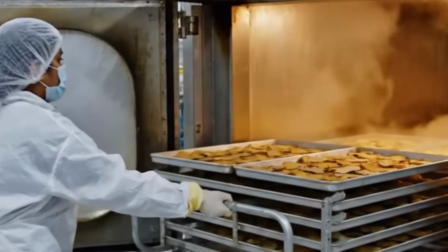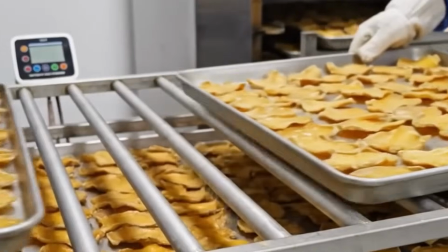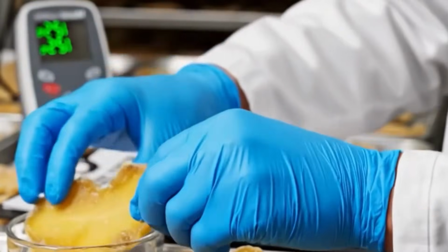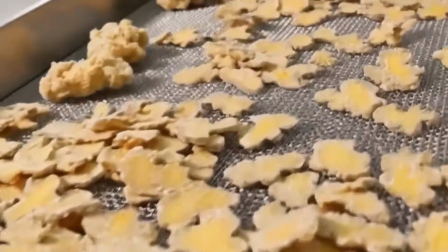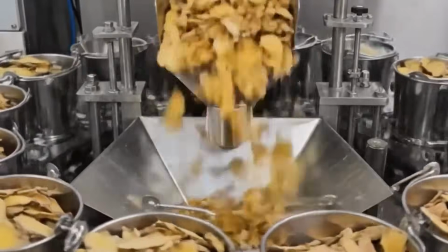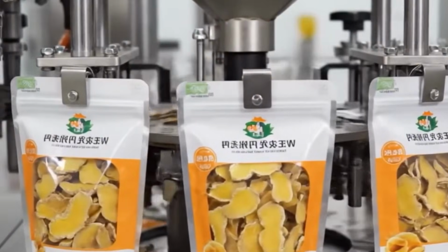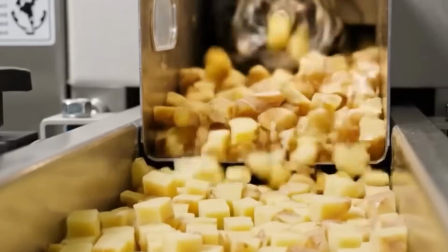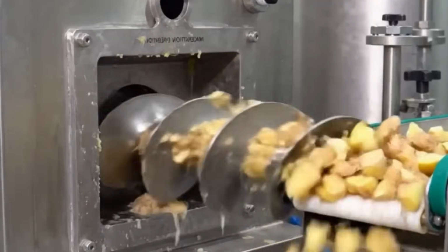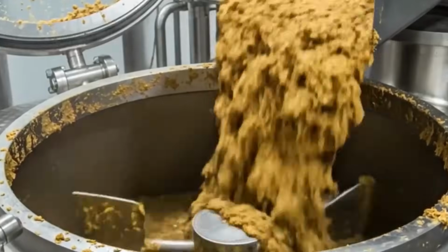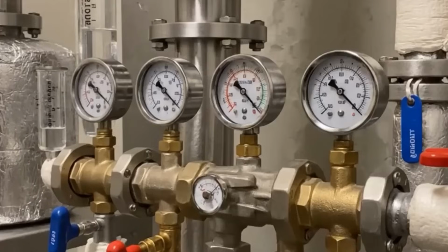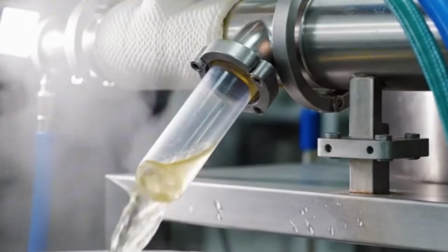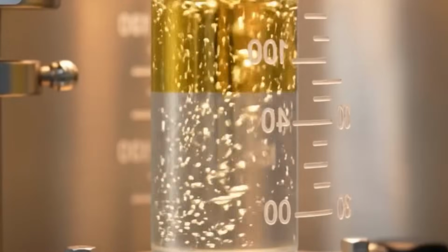This unit uses magnetically driven flow meters to monitor real-time volumetric flow of each stream. PID-controlled valves adjust the ratio continuously to maintain the programmed syrup-to-water proportion. The blend passes through a series of mixing chambers where turbulence is created, using static mixers to ensure full molecular integration. An inline refractometer measures the resulting Brix level, and adjustments are made automatically to ensure target sweetness is met within